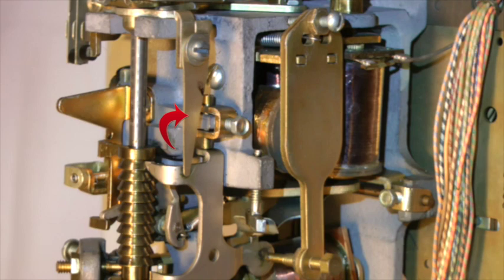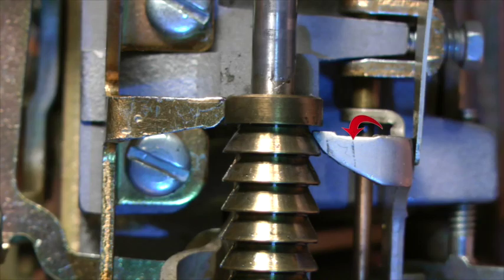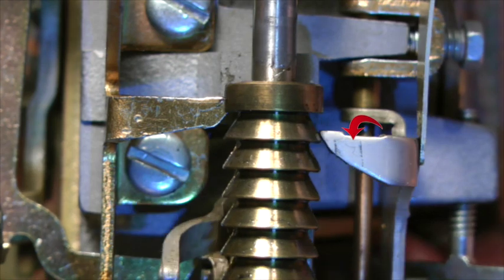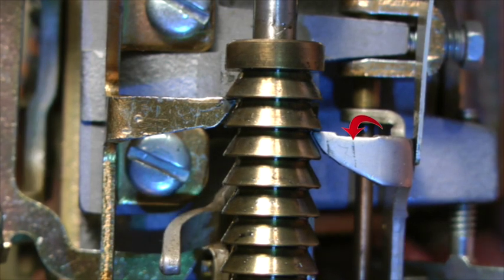Both the vertical and the rotary dogs are held pressed against their respective ratchets by the tension of this spring, which is appropriately called the double dog spring. During vertical stepping, the vertical dog leg prevents the shaft from slipping downwards between engagements of the vertical pawl.